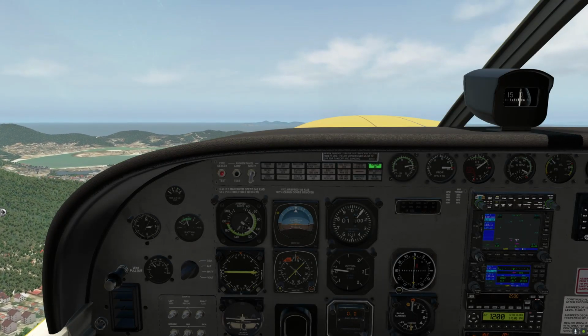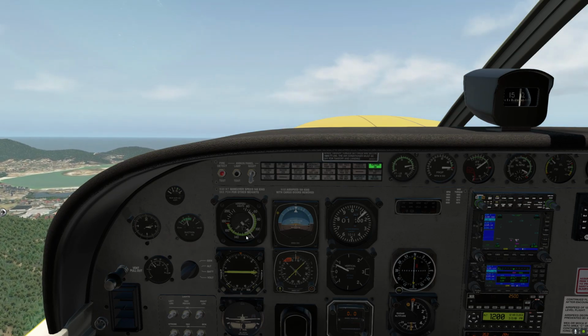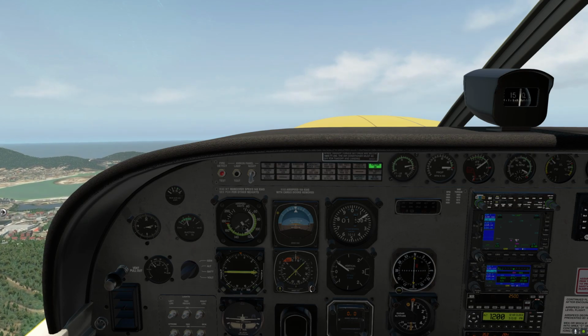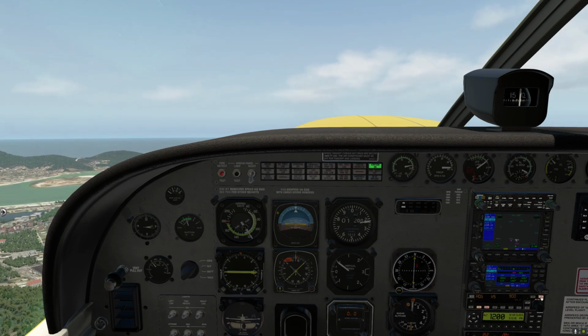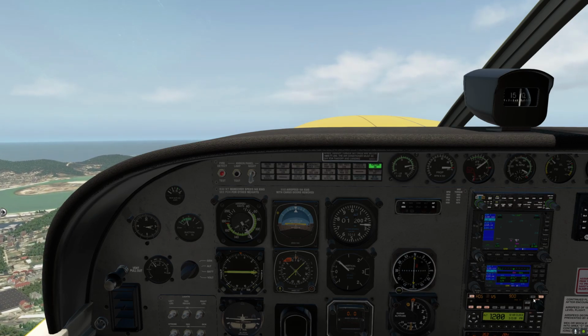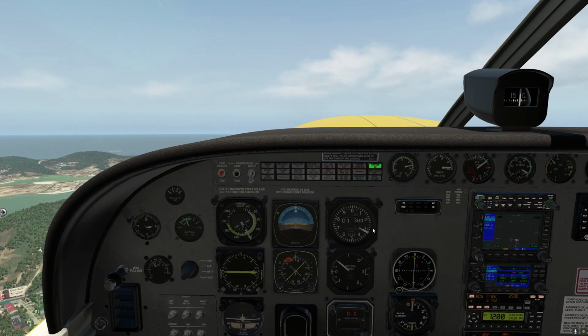So we've just taken off, we've got the flaps retracted. I'm going to accelerate up here to 120. And let's get the autopilot on. So I'm going to set the heading bug, autopilot altitude select is already there. I'm going to go heading, VS mode, servos, and arm that altitude select. So it should level us off at 2500.